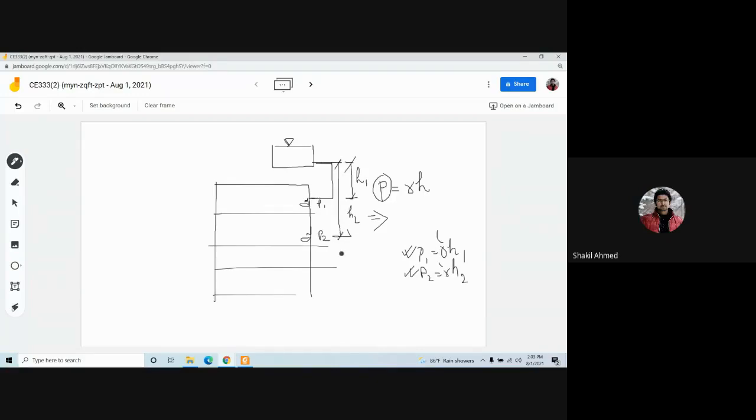So as you go downward for this down feed system, why? Because water is flowing downward. So this is a down feed system. In this down feed zone, who will get the minimum fixture pressure? The top one, right? The top fixture.